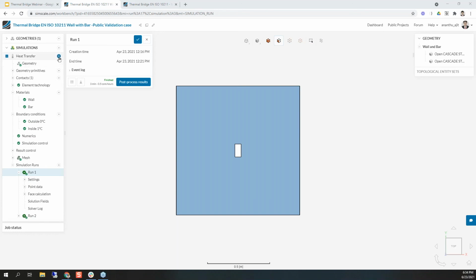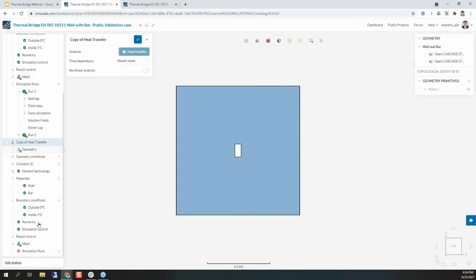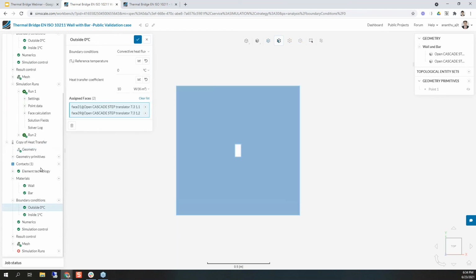I can actually show you how to duplicate the entire simulation. On screen, if we have a simulation that works, you can simply duplicate it. You'll get an exact copy, and then you can start changing the geometry or even the boundary conditions from that point, using this as a template. So I would say the workflow is made simple for design engineers to get access to the tool.